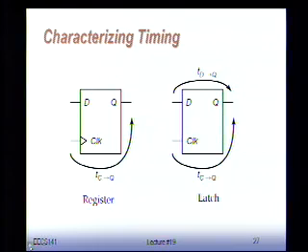Okay? Now, before going to the timing effect here, let's actually go forward on this. Now, remember gates. What do we care about in a gate in terms of timing? The logic functionality is clear, right? You have latches, you have registers. Let's think a little bit about the timing characteristics. For a gate, we basically worry about propagation delay, right? Propagation delay is the delay between an input change and an output change. We take the 50% point, and it can vary between the different inputs.